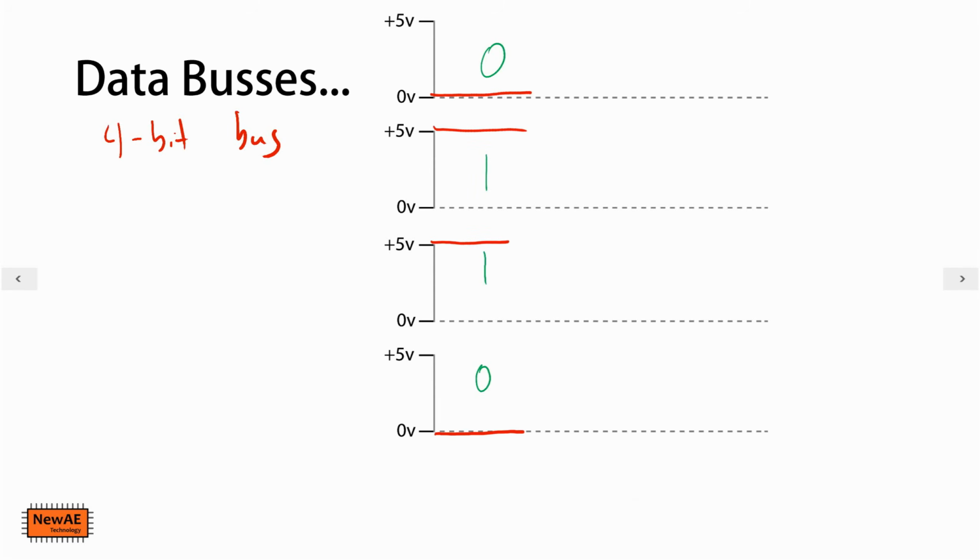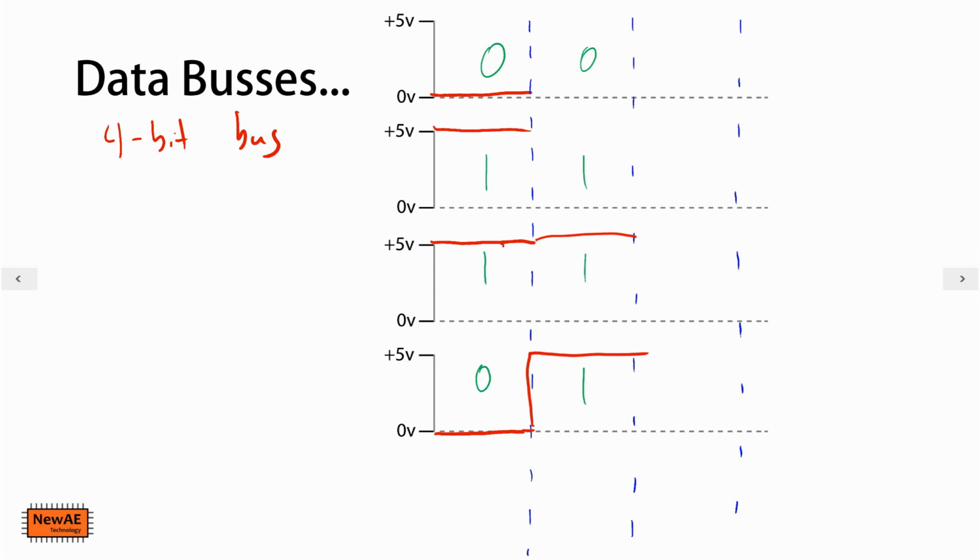On the physical device, it's then going to increment this number. Now it increments it using a clock, so I'll draw this dotted line to show when it'll change state. And we'll have a few of these, so let's add a few more. There we go. So at this point here, what's going to happen is it's going to increment this number, and this number will become 0, 1, 1, 1. And so we can say, okay, well, this one will go from 0 to 1. This one will stay 1. This one will stay 1. This one will stay 0.